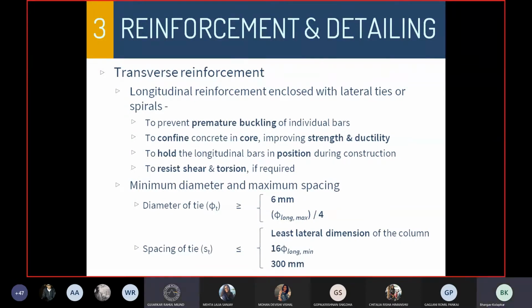To resist the shear, I guess. Yes, simple. To resist shear and torsion. Similarly, now if you look at columns, they are going to be subjected to compression and they may be subjected to flexion. Providing concrete and longitudinal reinforcement should suffice.